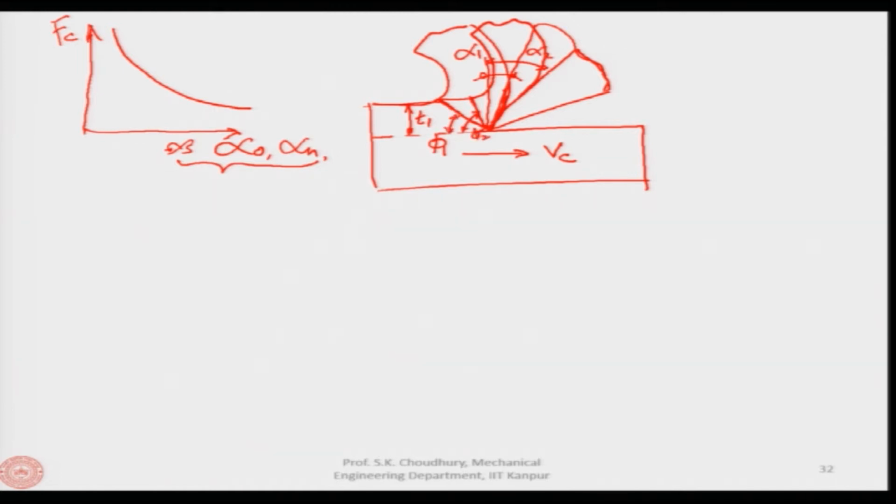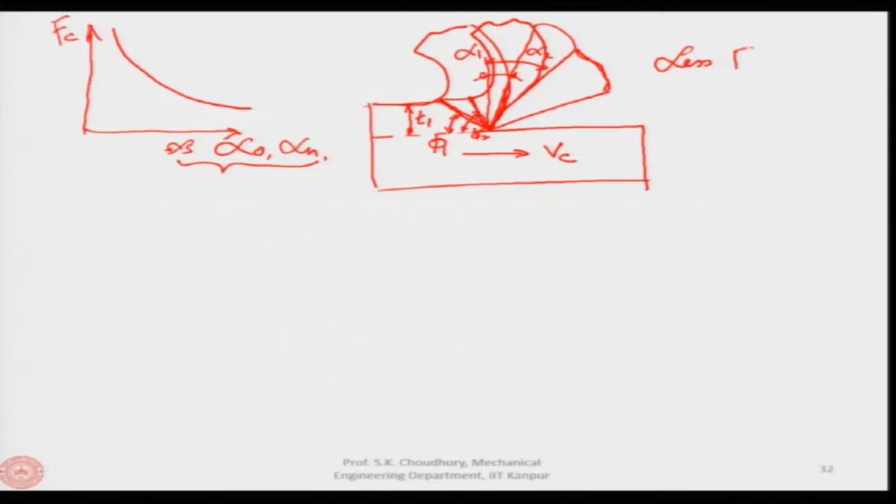So overall, the shear plane is decreasing in length. Therefore, less material will be sheared, the force and the power consumption will be less, and the surface finish will be better, because the force applied to the process will be less. So, less cutting force Fc. The power we will discuss in detail later.